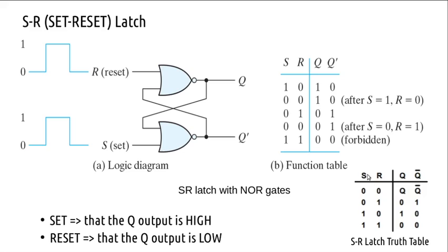We usually draw only the truth table, but we'll use a function table to explain this case as well. Here the don't care last case is written, and the 0 case is written. When 0 comes, it retains the previous value. With 1 0, it was retained, right? Same case here, say 0 1, you are resetting this flip-flop, and then you apply 0 0, that is retained.